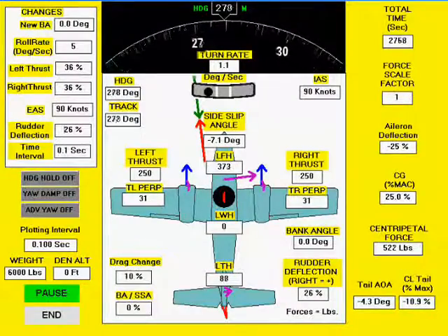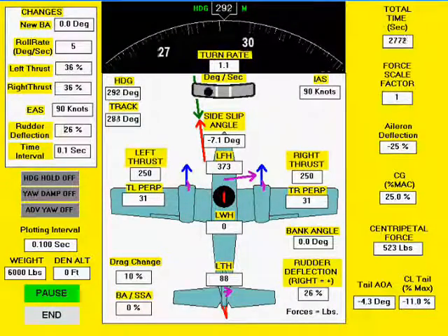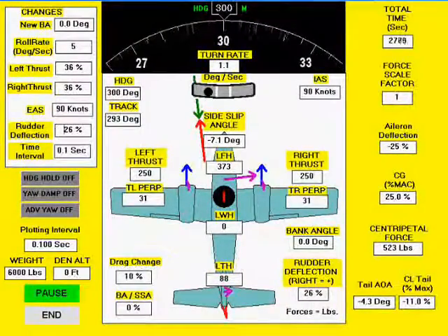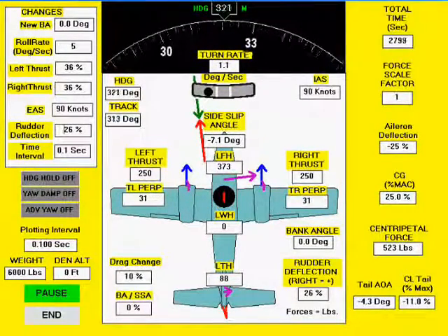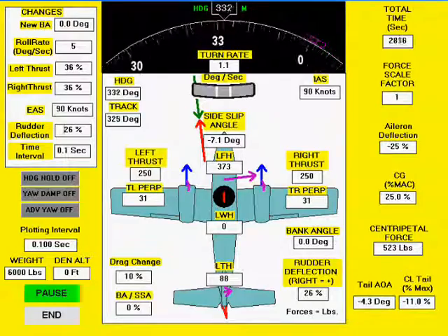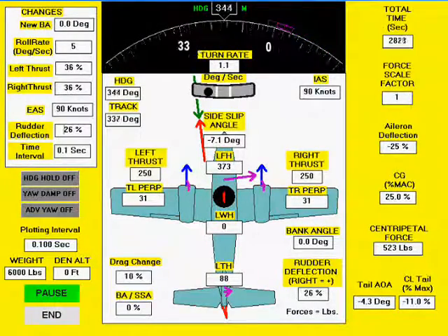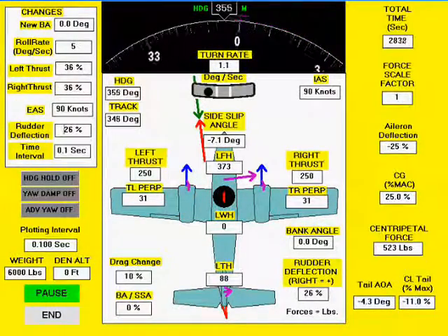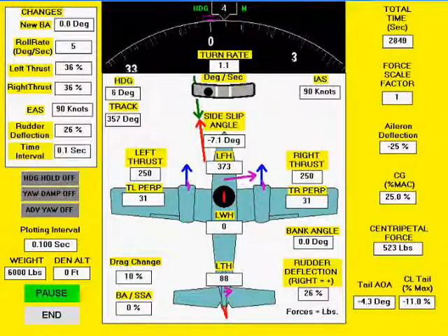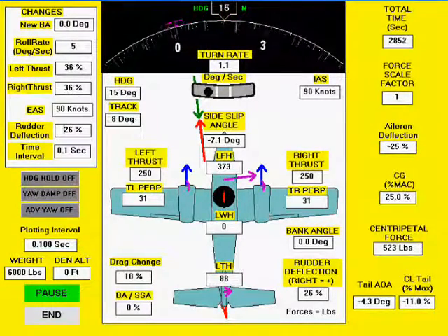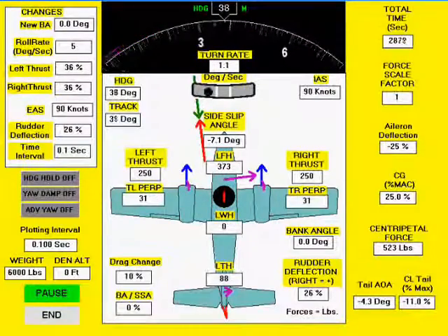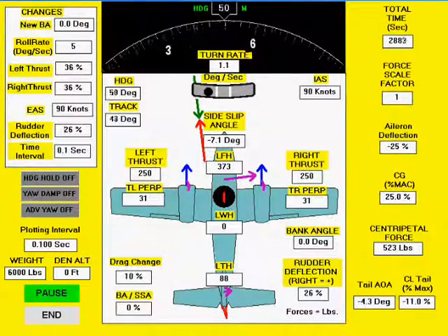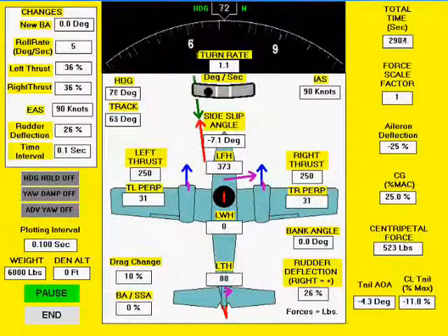This produces fuselage lift, which is perpendicular to the relative wind. Think of the fuselage as a thick symmetrical wing with a very short span turned on its side. The combination of fuselage lift, tail lift, and horizontal components of thrust provide the centripetal force that creates the turn. Note that this centripetal force is approximately the same as the value created by a 5-degree bank angle and produces the same rate of turn.